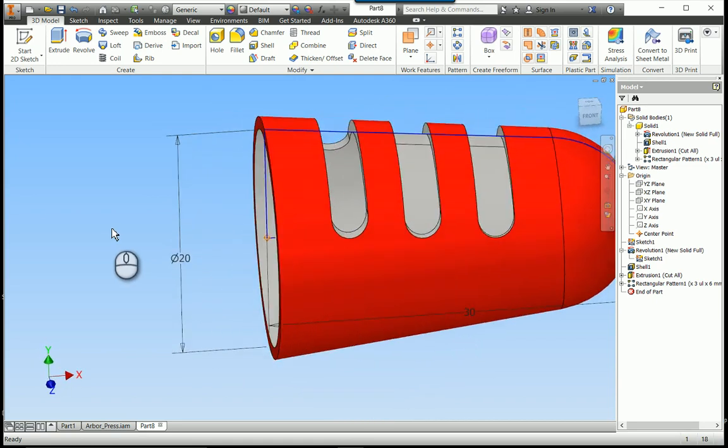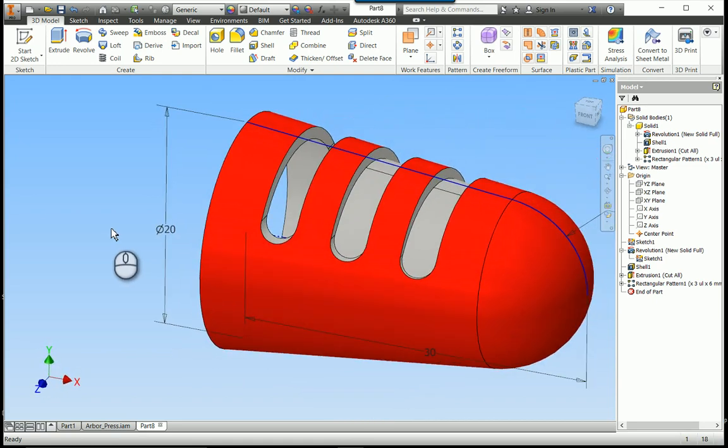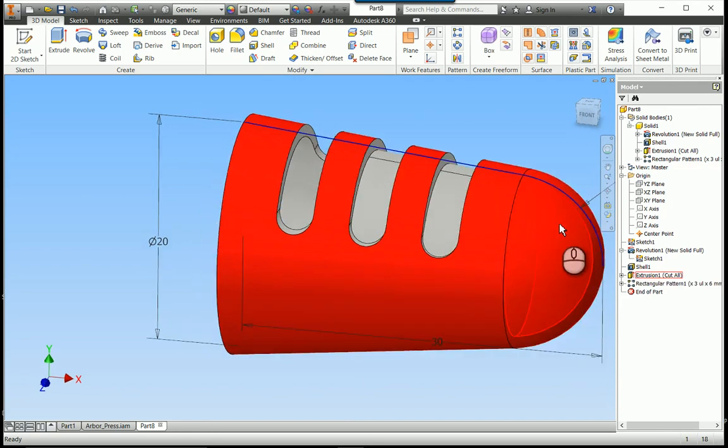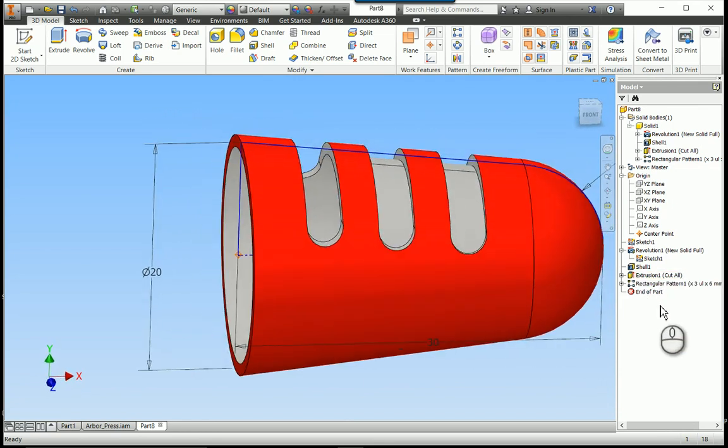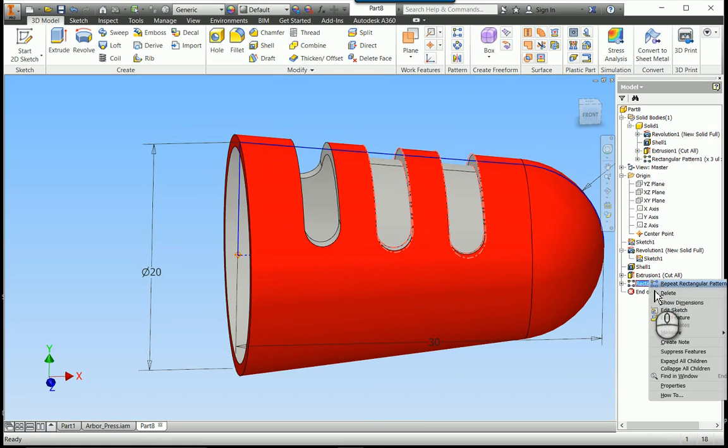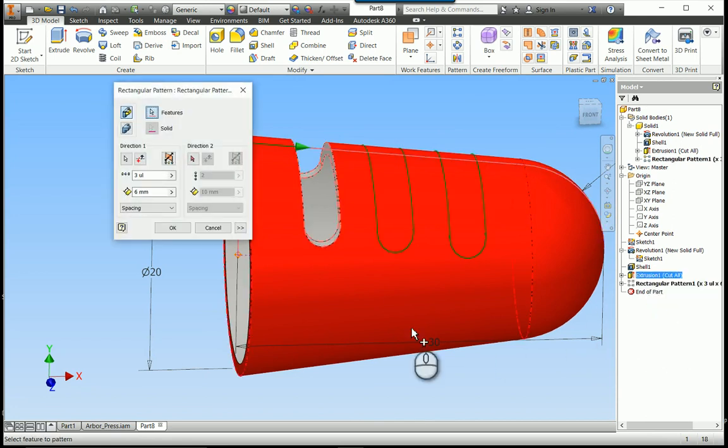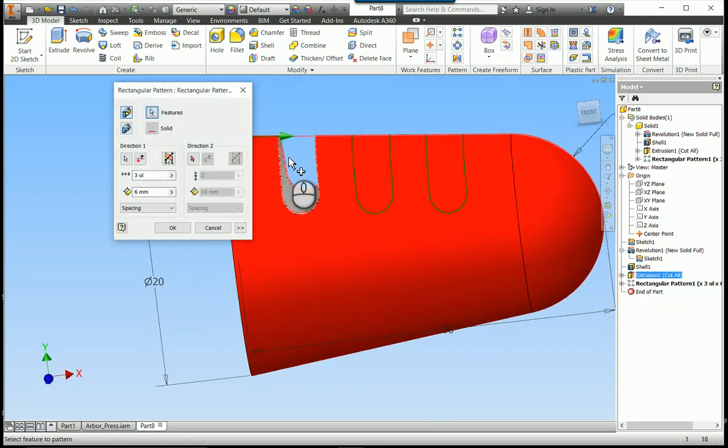And here's what happens when I make this cut. Let's see if I can get a preview here to help visualize what's happening. I'm not sure I'm going to be able to get what I want. Let's edit this feature. Well, it's cutting the same material out here as though this was going straight along here rather than at that angle. So it's the identical material, so it's trying to pattern that identical material that it cut here and here, but the problem is it's going along this angle.